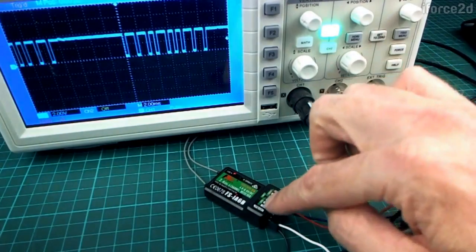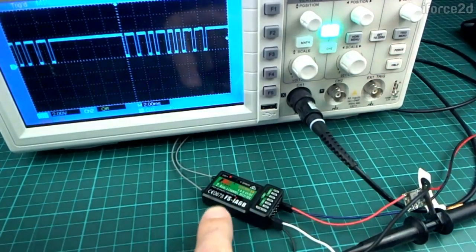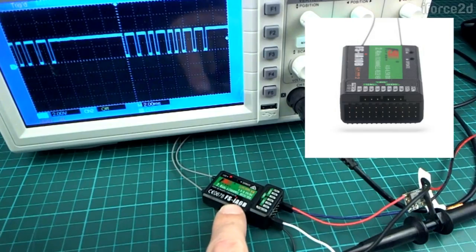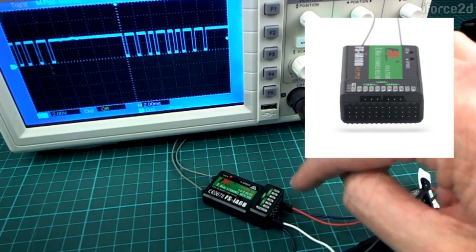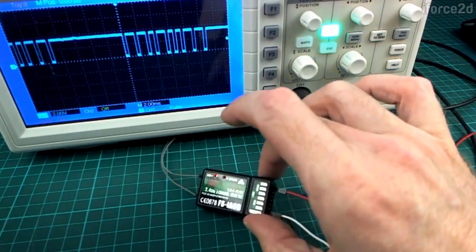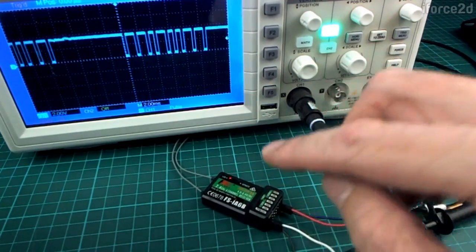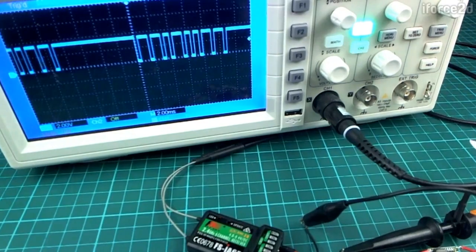Some receivers already come with more than 6 pins, so you can buy one of these that's, I think, an FS-iA10B or something like that, and it has 10 pins, so you can use 10 pins using normal PWM if you want to. But for this one, going from 6 channels to 8 channels by using PPM is a nice advantage. So now that we know how PWM and PPM protocols work, there's just one other thing I wanted